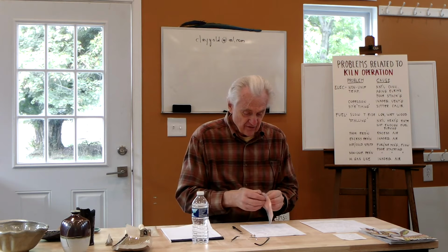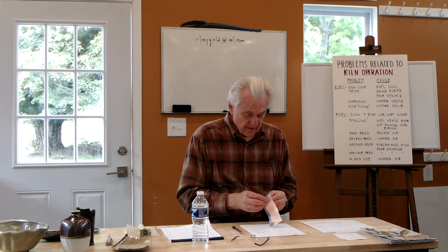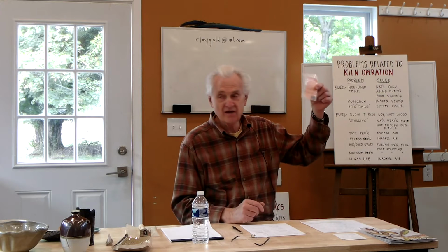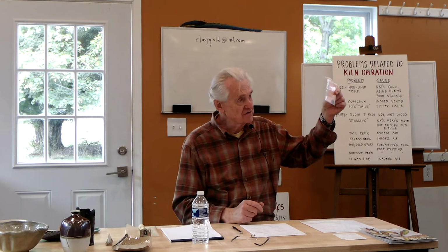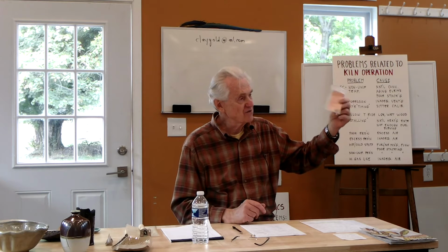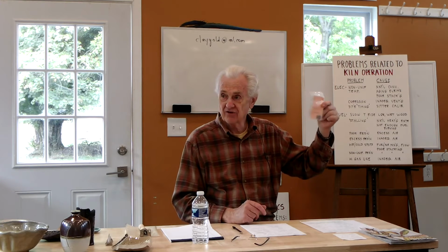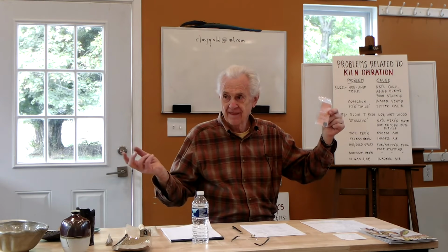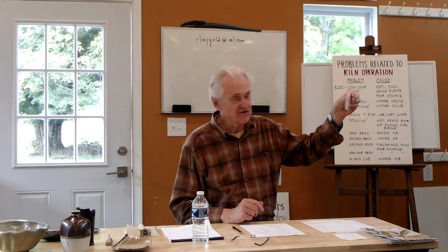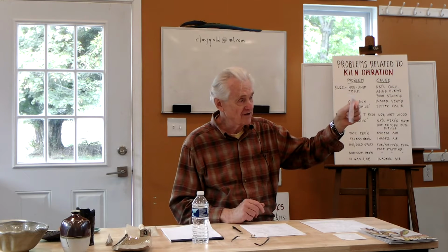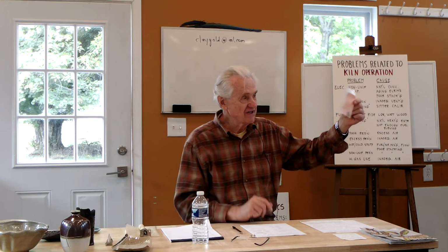And if you got the kiln new, there was a little gauge that came with the kiln, and this is actually used for adjusting the kiln sitter. I was telling Dennis earlier this morning, a lot of times when you buy a new kiln, this comes shipped on the kiln sitter, and people think it's just a packing device and they throw it away. Actually, this is the gauge that you use to adjust the kiln sitter. So it comes shipped on it so that it doesn't bounce around, but you need to save it.